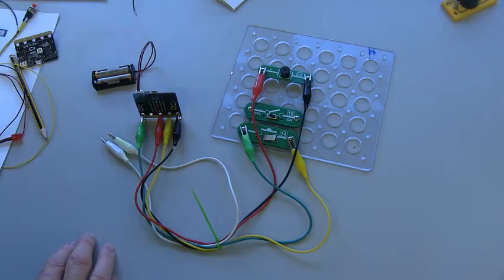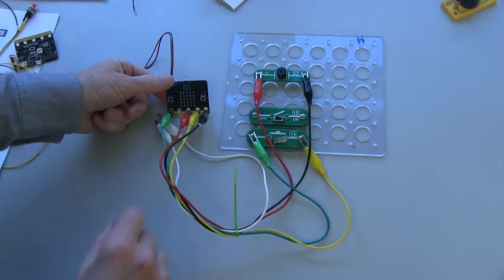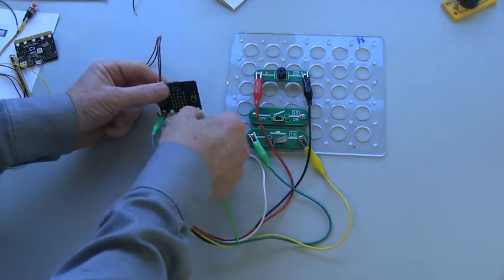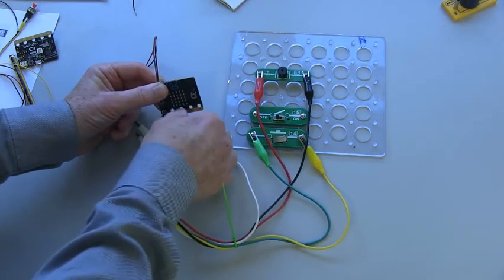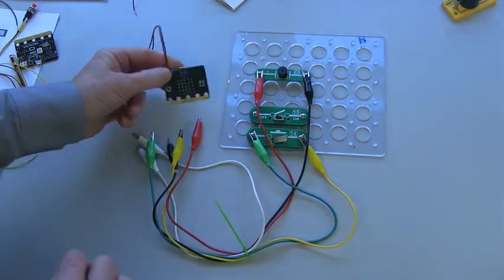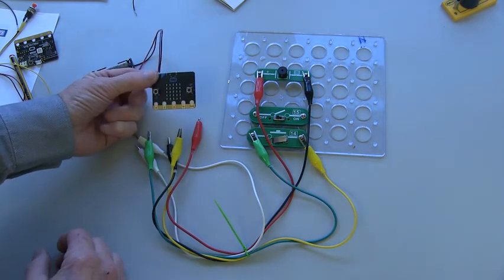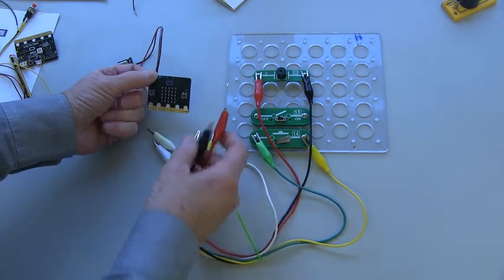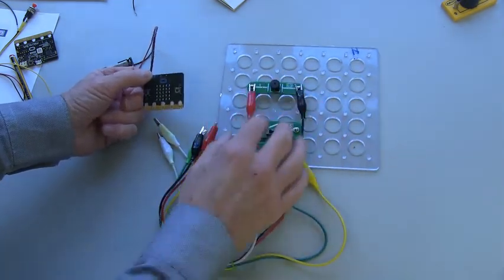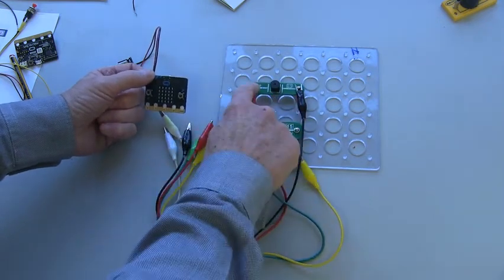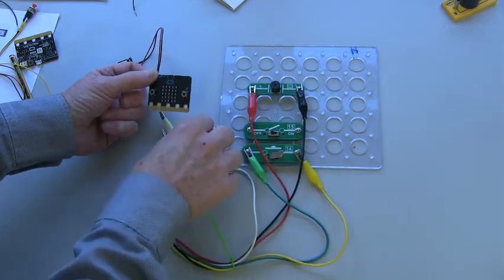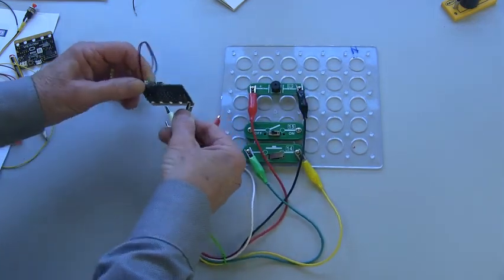In lesson 9, the project is to build a burglar alarm, and so we need inputs. So just to quickly take you through the circuit in lesson 9, the lesson is fully explained, but if I just disconnect this microbit, I'll show you what we've got here. So the output side is very similar to lesson 4, except in this case we're controlling a buzzer. I've got a 3-volt buzzer here, and that's got to be connected the right way round. So I put the red wire to positive and the black wire to negative. That reminds me the black wire goes in ground.